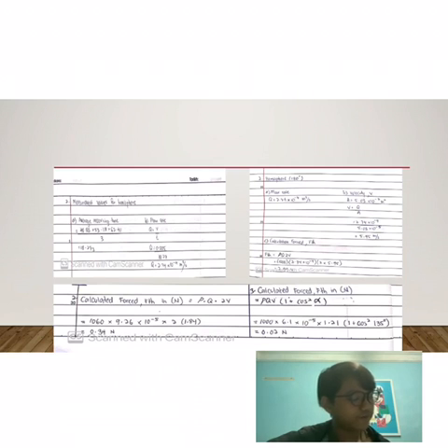Calculation of force F equals P Q 2V. For P we have 1000, for Q we have 2.74 times 10 power of -4, and for 2V we must do 2 times the velocity, which is 5.45, and it equals 2.99 N, which is Newton.